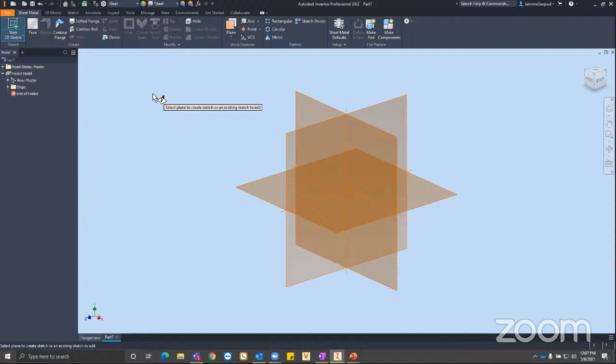So choosing the material that you're actually going to be using can affect your tolerances whenever you're going to bend. There are many things that can affect your bend, especially how you're going to bend, what press brake you're using, what tool you're using, but it's good to actually have your material set correctly. That way the K factor can be accounted for. Okay, that's good to know.